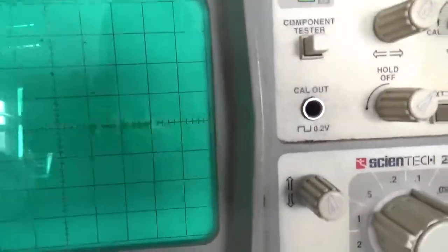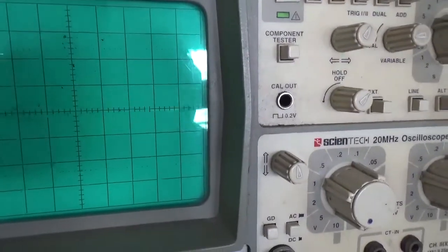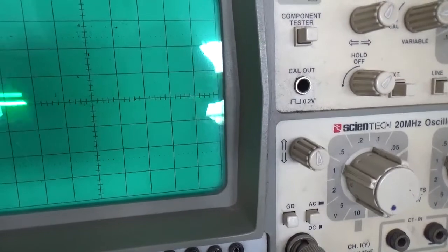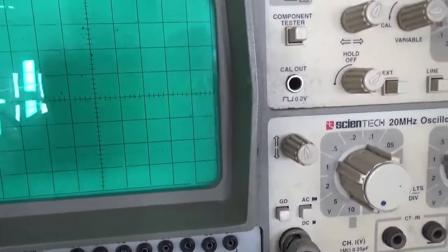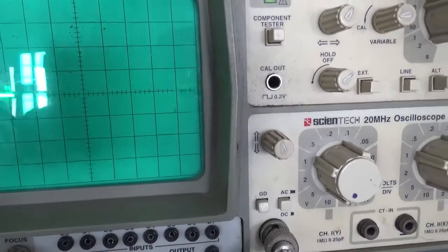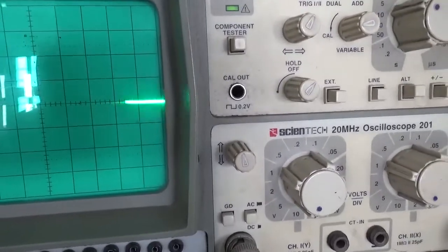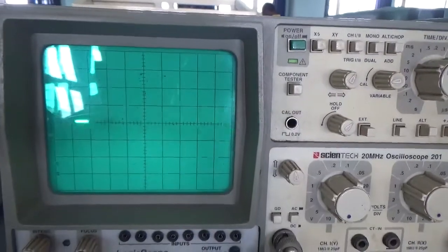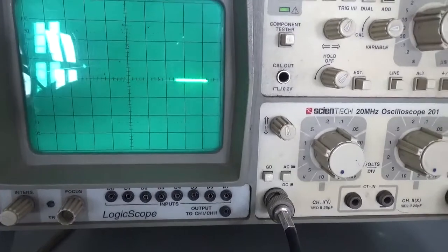G1 K1 is the firing pulses. You can see the firing pulses. I am showing very near. And then let me change the values. Suppose I am going to 1, 3, 7. Then you can see the on time of the firing pulses is reducing there. And this is 15. At 15, you are getting a small spike there. So the respective firing angle is increased towards 180 degrees.